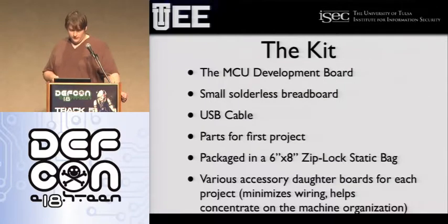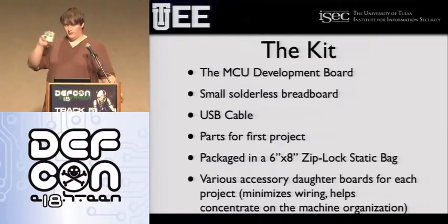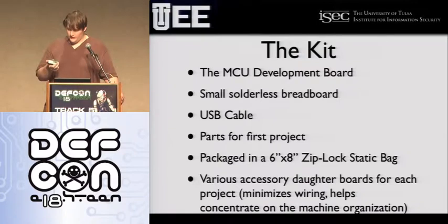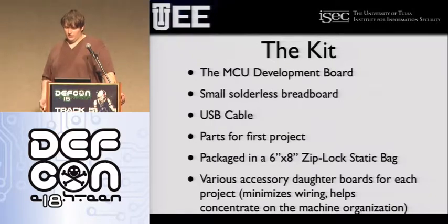The kit itself contains the development board, which is tiny, and a solderless breadboard. I don't know if anyone can see this, but we give them a little breadboard so that they can hook up accessories that we've built, or LEDs or anything that they've got. And we put it in a 6x8 static bag. And the reason being that most people don't know about properly handling electronics. So putting it in a static bag and explaining static safety is part of the curriculum we developed. And we kind of discovered that there's some problems with static safety unless you beat them over the head about it. So we'll talk about that again in a minute.